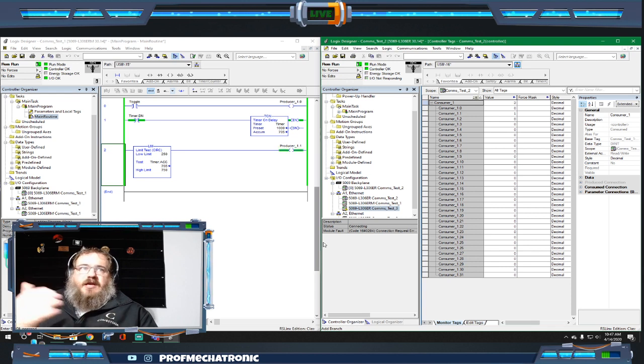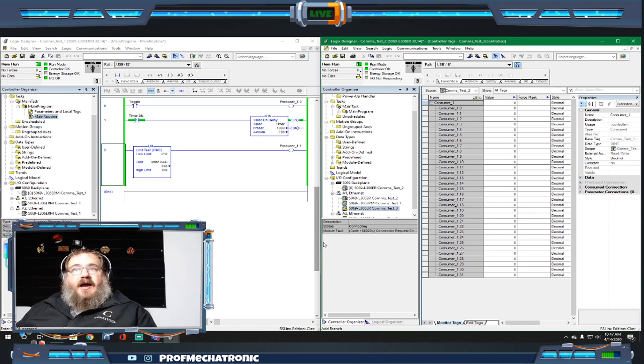You want to make sure that you understand. You have to go online and offline to your PLC and download a bunch of times. So you will error out and you will stop the process when you're setting this stuff up. But once it's set up, then you're off to the races. So there's some huge advantages to that. So you also want to make sure that when you do set this stuff up that you give yourself some room. If you only needed 10 bits, I wouldn't suggest only setting up 10. Make sure you set up all 32 or set up 2 words of 32 so that you have lots of spares so you don't have to redo this all the time. Once it's set up, you're in good shape to move forward.